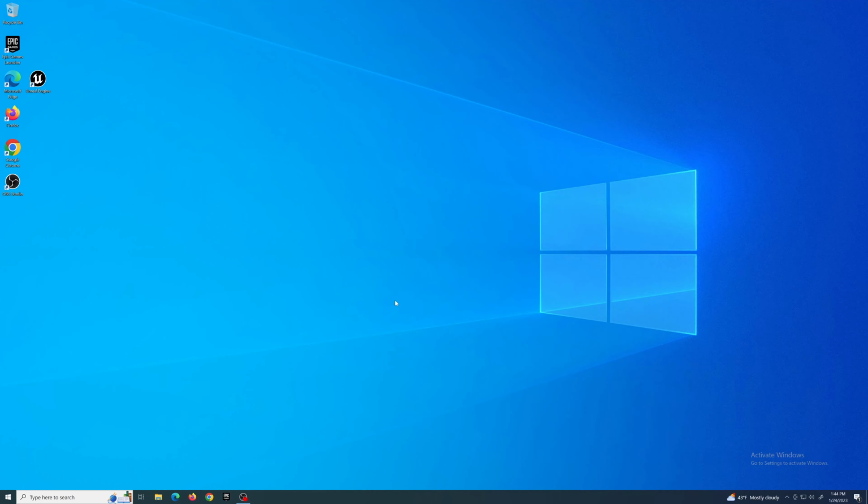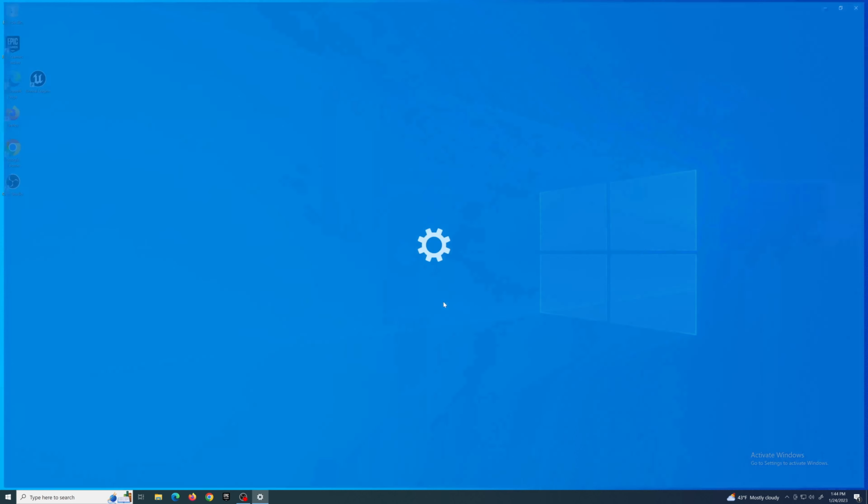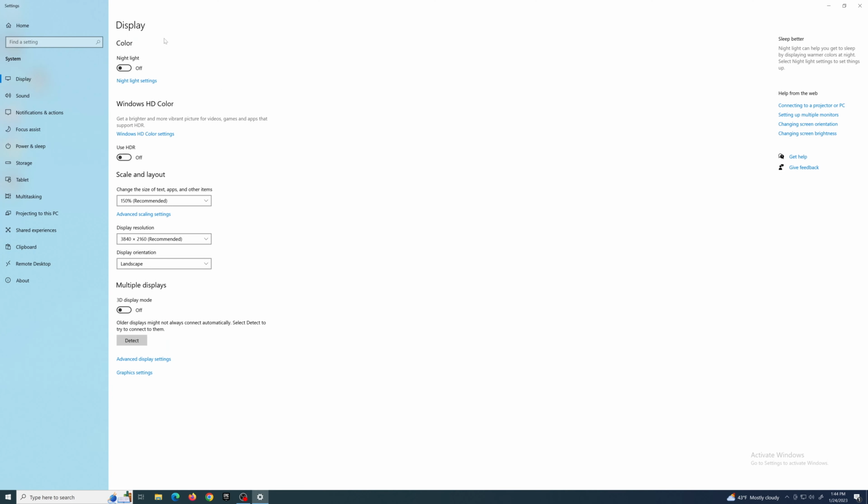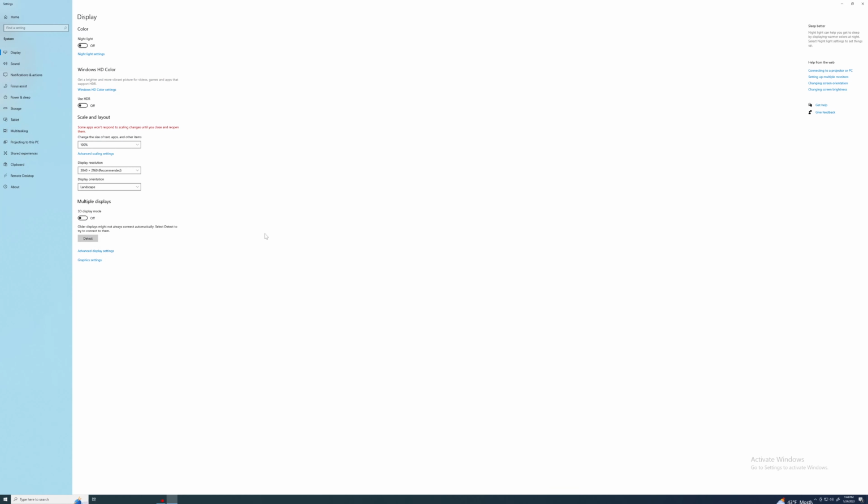Okay, so the first thing we're going to look at is some display settings. If you just right click on your desktop and then hit Display settings, first it's going to load up your display. If you have multiple displays plugged in, this window would look a little different and you'd see there's two displays. We want to take a look at scale. We want our desktop to render always at 100% if this is going to be our rendering machine.